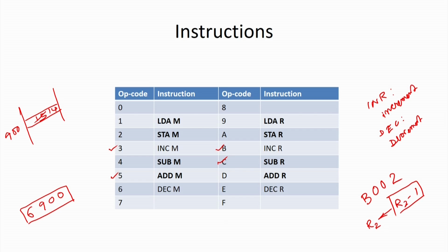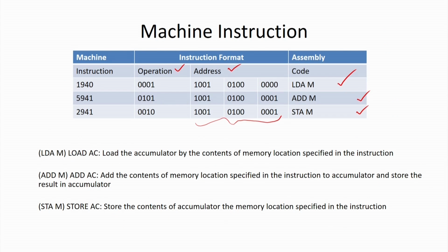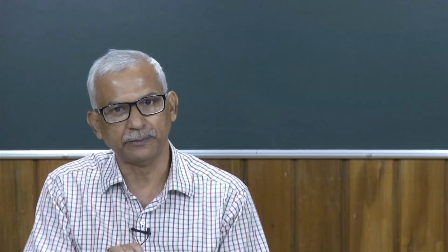Now, when we are using increment and decrement operation in processor, generally we are not going to use the ALU for such type of organization, because here we are having some values in the accumulator. If I am going to use accumulator to decrement it, then we have to bring it from the register to the accumulator. So, it will get disturbed, that means temporarily we have to store the value of accumulator. So, instead of doing it, what generally we used to do? We are going to put a specialized circuit over here, which is going to increment it or decrement it.